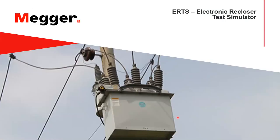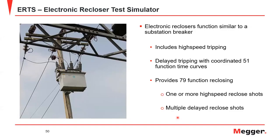Okay, so now we're going to jump into electronic recloser testing. So in general, reclosers, with regard to reclosing, are very similar to a breaker. Both a recloser on a pole or in a switchgear and a breaker in a substation provide multi-layers of high-speed tripping, time-delayed tripping, high-speed reclosing, delayed reclosing. They function very similar with regard to their basic trip and reclose functions. So how do you test them?